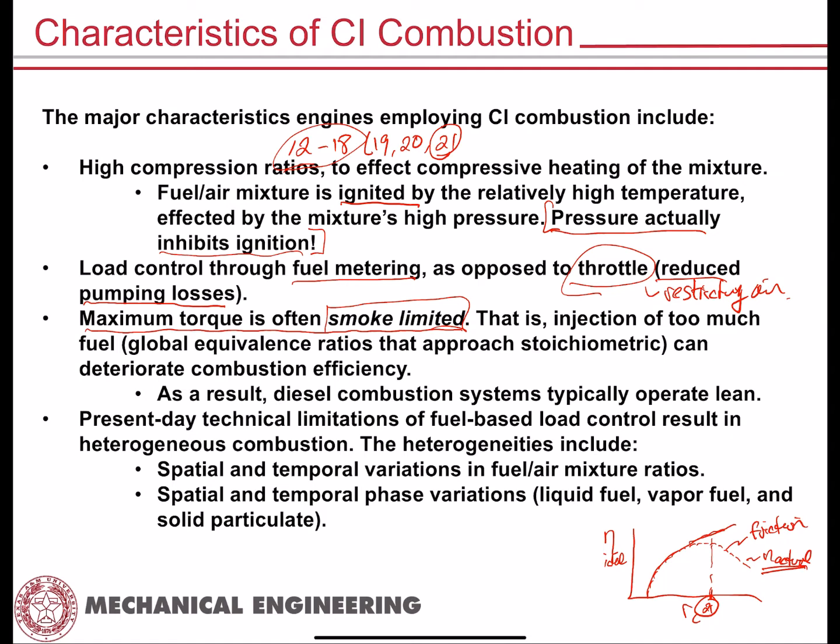And as that flow penetrates, it starts to mushroom, right, toward the leading edge of the injected fuel, right? So the fuel that's furthest away from the fuel injector starts to mushroom out, right, and kind of get entrained by the air, okay? That mushrooming out is what we call spray breakup, okay?